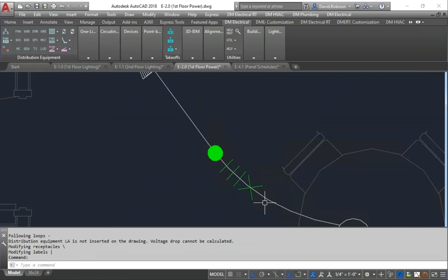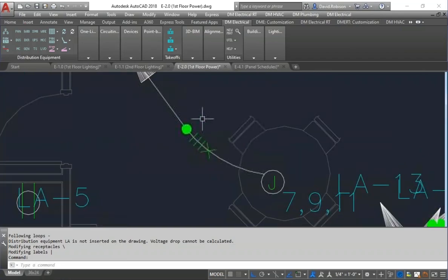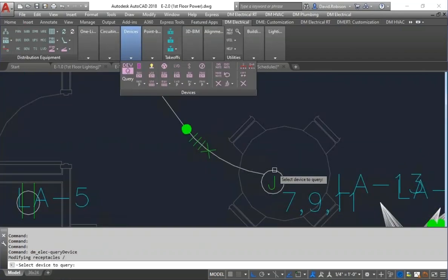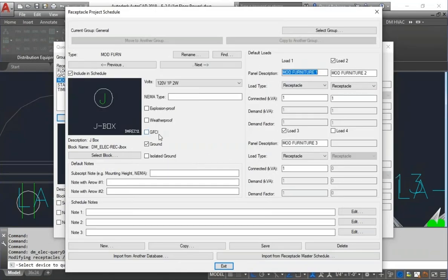There are a couple of other things you could do with tick marks. There's also the question, what if that's not the actual configuration of wires? The answer is you have to go back to your model and get it set up so that you do have the right configuration of wires. For example, say there's no ground on this. You would need to come back here, modify this receptacle, and remove the ground wire, because we're including a ground since it was specified to have one. And if you don't want a ground, you have to get that ground out of there.